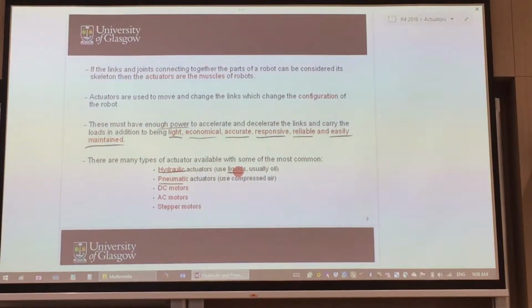There's a difference between using water and oil. Water, being less viscous, is prone to leaking. So there's a small little gap between the seal and the piston, and then the water is going to leak out. The good thing about water is that it's not a fire hazard. In fact, it doesn't catch fire. So you can use water hydraulics in things like the aerospace industry.